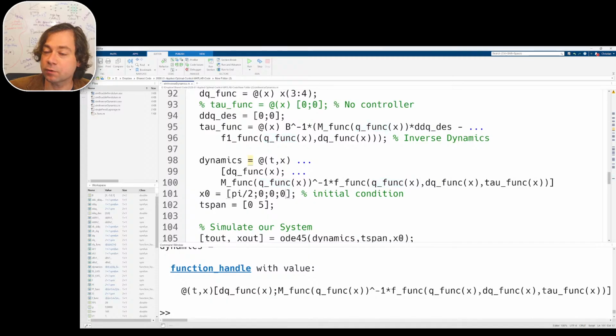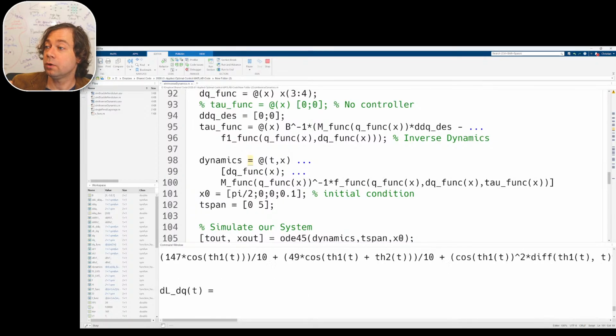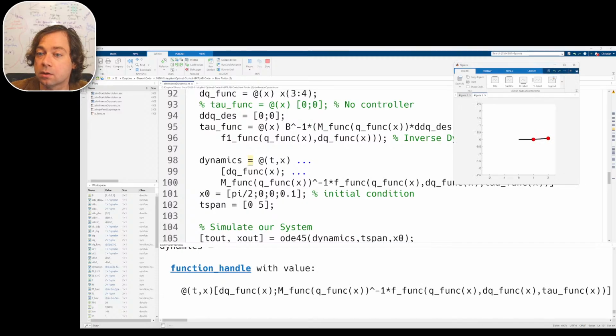Let me make my starting velocity of my last link like 0.1, okay? A very slow starting velocity. So that second link should keep spinning at constant angular speed, not being accelerated, because the acceleration desired is 0. Let's watch what happens. So 0.1, what happens? Look at that. Spinning with constant speed.